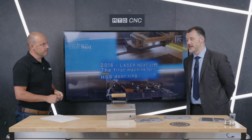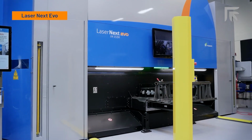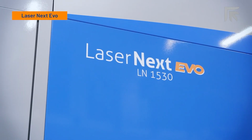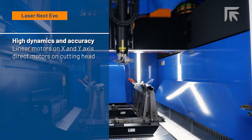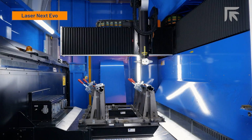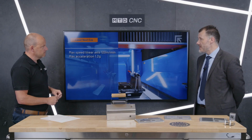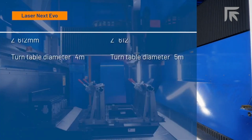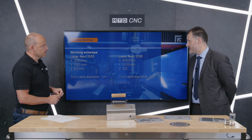Okay, so with the 3D laser technology, basically what we do is we have more of a multi-axis CNC type machine, kind of like a robot that is able to get round a part, however large that part may be, in order to access the peripheries and any areas that want cutting or indeed welding, using a long range head, as you'll see on the video here, that is able to access all of the extremities of the part. With 2D laser, it's slightly different. That's a flat sheet or flat plate application where we're cutting flat product. So we don't need to have such an advanced situation where we're controlling the head from a Z point of view in terms of its height and its orientation.